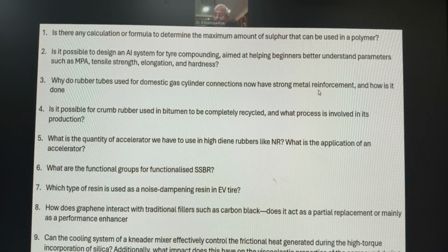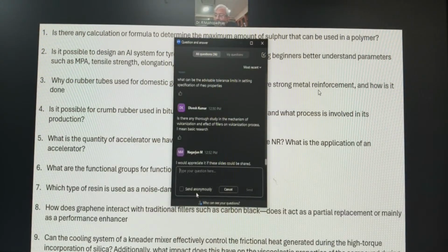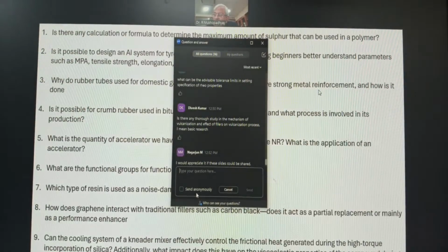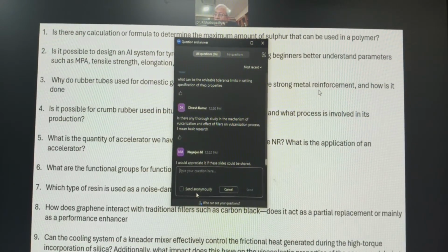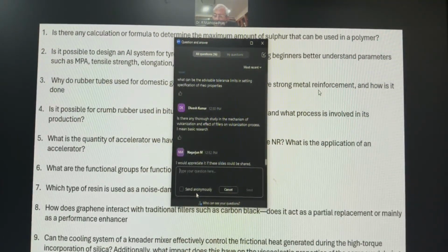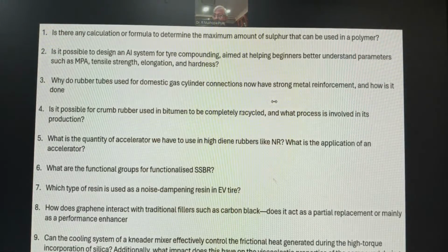Sulfur is used in the rubber industry at 1 to 3 phr, or maximum 5. But between 5 to 20 phr, sulfur gives a leathery stage in rubber vulcanization. Generally, after about 25 to 30 phr, you get ebonite. So if sulfur is used in higher doses, the maximum torque and hardness are increased, so that is not usable.